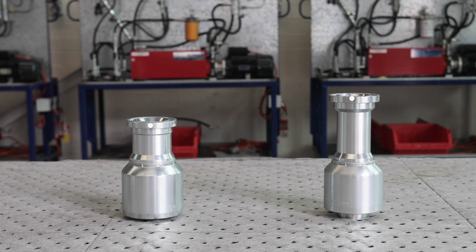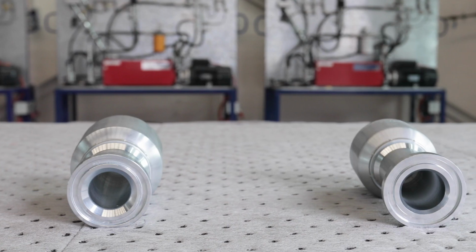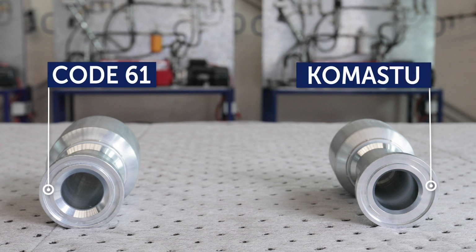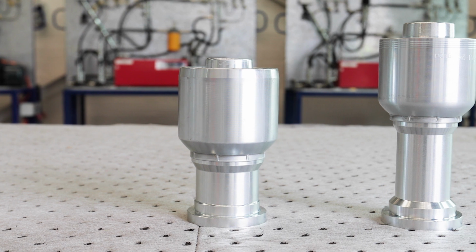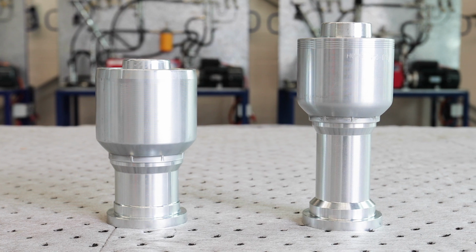Looking at these images, it may be difficult to see the important differences at the flange. This selection of hose tails are both rated at 3,000 psi and consists of Code 61 and Komatsu hose tails. Looking at the Code 61 and Komatsu hose tails, the flanges appear to be nearly identical. The difference here being, the O-ring groove in the Code 61 is imperial, while the O-ring groove in the flange for the Komatsu hose tail is metric. So, while there is only a small difference in these flange sizes, the flange clamps for Code 61 and Komatsu are compatible with each other.